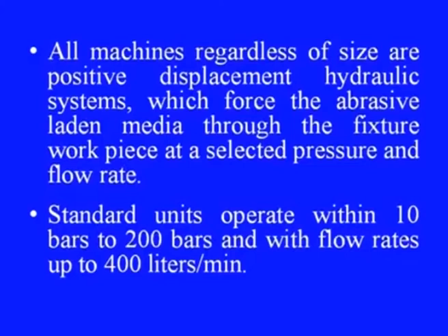All machines, regardless of size, are positive displacement hydraulic systems, which force the abrasive laden media through the fixture and workpiece at a selected pressure and flow rate. Standard units operate within 10 bars to 200 bars and with flow rates up to 400 liters per minute.